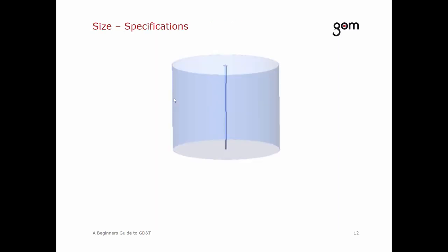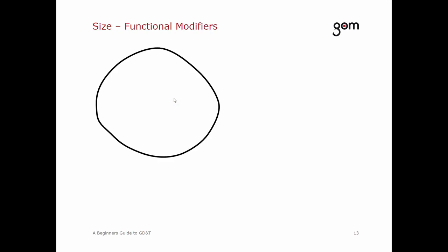So this is a specification of which I'm sure you've all seen many times before. However, what does that actually mean? Let me make this more plain with this example. Let's assume that the measured cylinder looks in a section view like this. It is possible to calculate the minimum and maximum size for this. This is called a 2-point size.